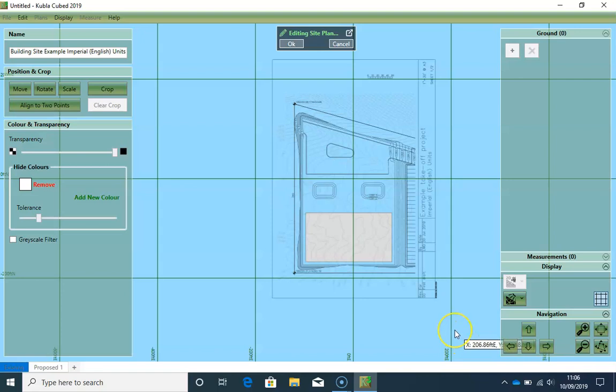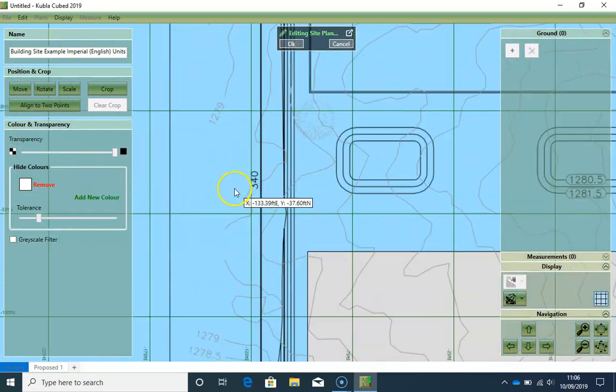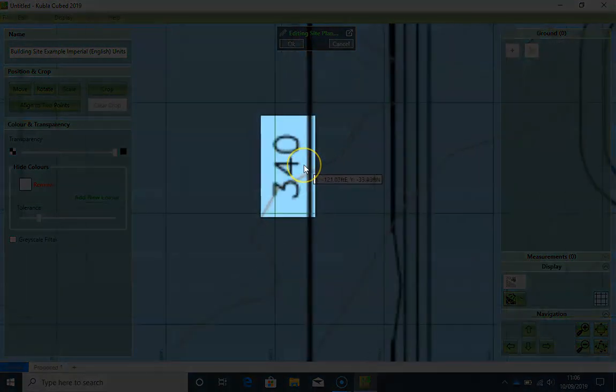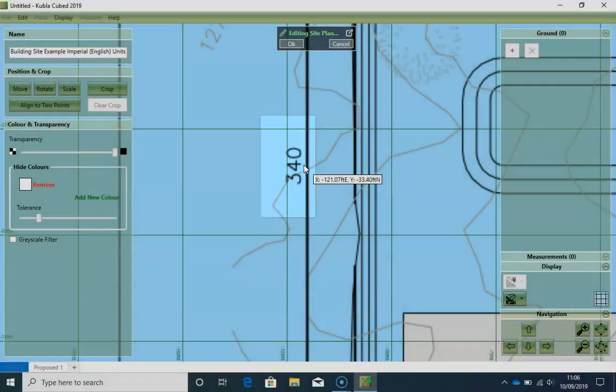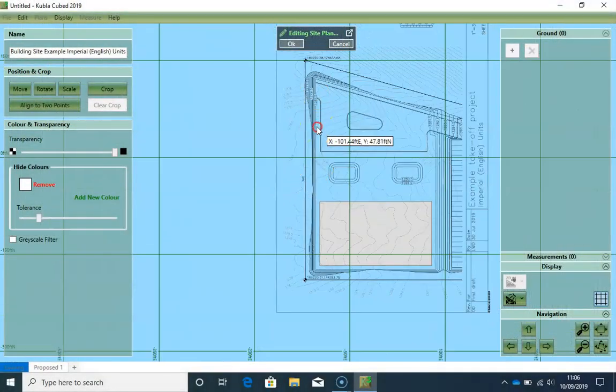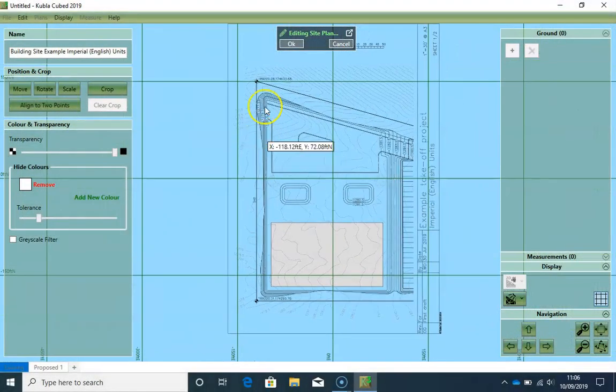Now, obviously, if the scale is wrong, then all volumes will be wrong. Therefore, never forget to check whether you have scaled correctly to see whether the software provides you the same value as the drawing. For example, here we can check the length of this marked length, whether the software will give us the same value, 340 feet.